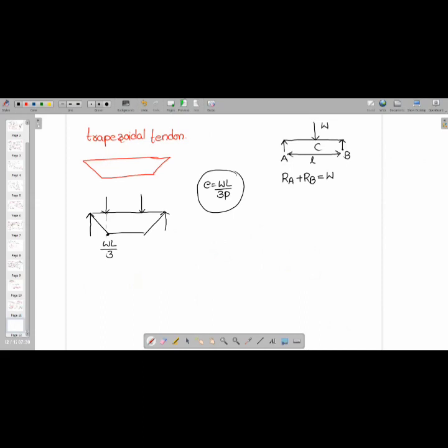Now see, students, what I would like to tell you here is that at simply supported ends, the moment will be 0. So if I consider moment at B equal to 0, this will be RA into L. That means this is acting down, meaning clockwise.